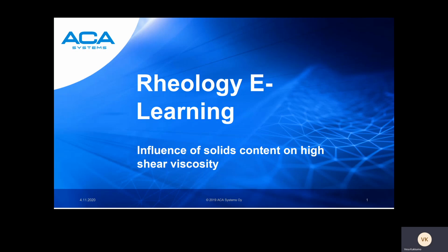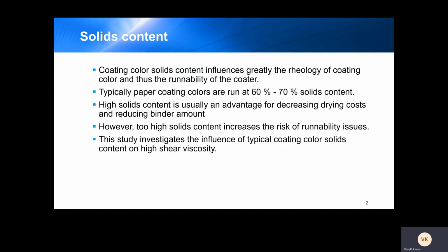Today our topic is influence of solids content on the high shear viscosity. Solids content, we know that coating color solids content influences greatly the rheology of coating color and the runnability of the coater. It's typically 60 to 70% solids content of coating color that are runnable in high-speed coaters.